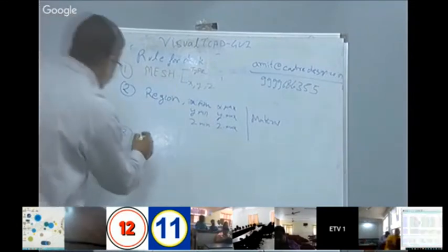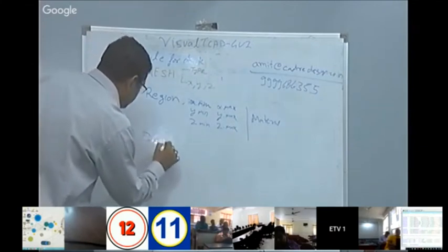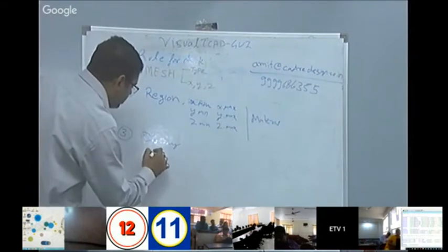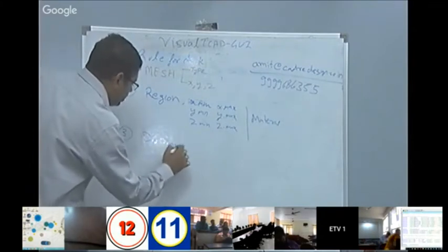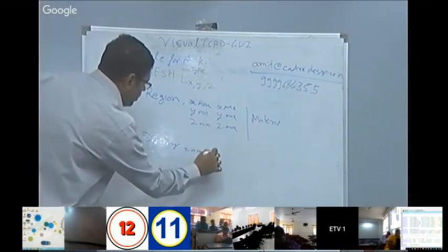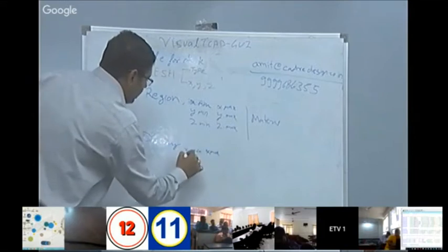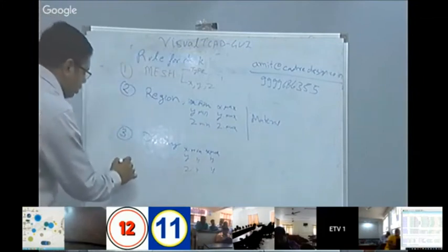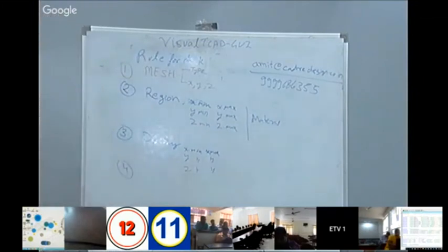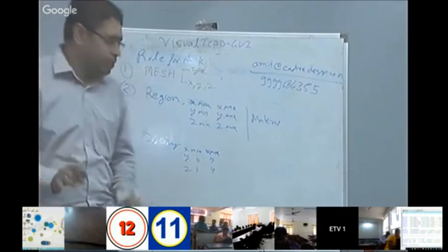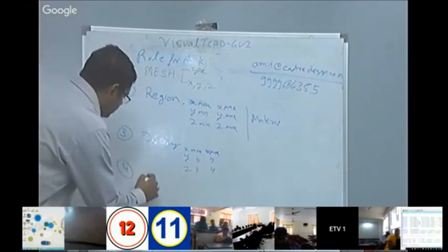if doping, here also we define regions. In the doping, we also define coordinates: x minimum, x maximum, similarly y, similarly z. Fourth, we define mesh, region, doping. Till here, our device is completed. Then we export the device.